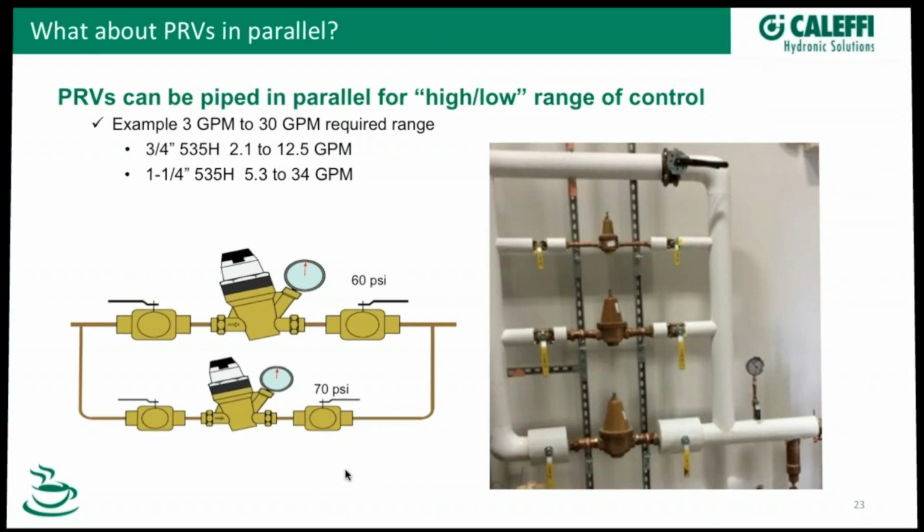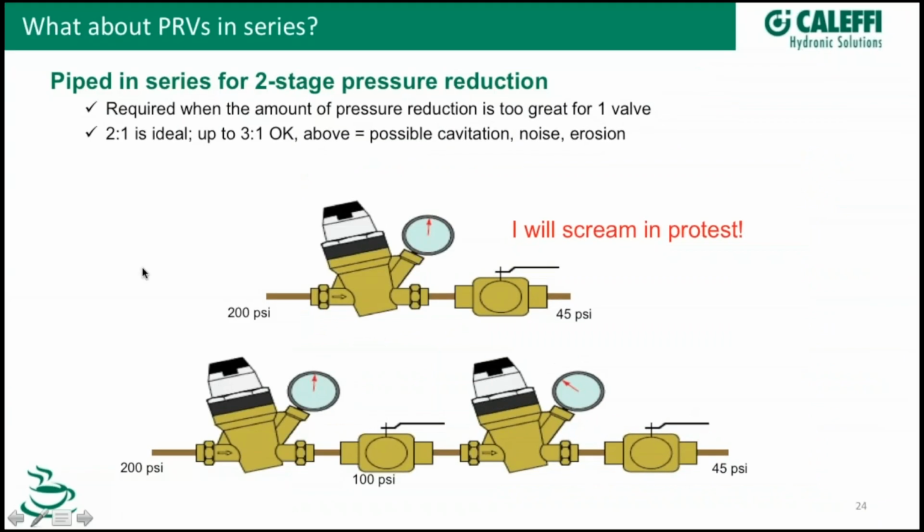Well put. Yeah. And then when you talk about pressure in buildings, you can talk about scenarios, like I said before, where you're going to have 300 psi, and there's typical ratios for inlet to outlet pressure on these pressure reducing valves, and what Bob's underlining there is your ideal ratio is going to be 2 to 1. And the idea there is, say, for example, you got 100 psi coming into the building, you got to knock that down. You don't want to knock it down any lower than 50 psi. So that would be a 2 to 1 ratio.